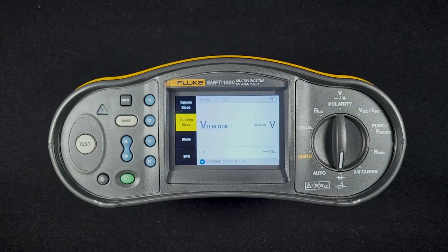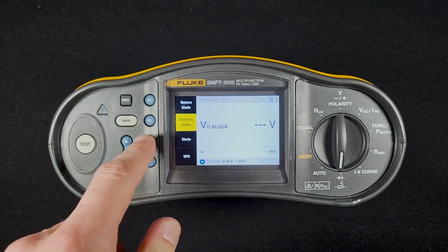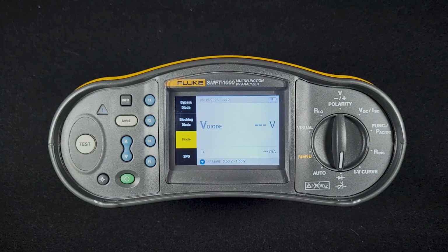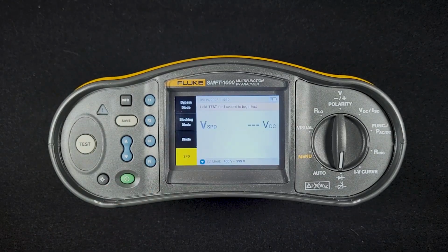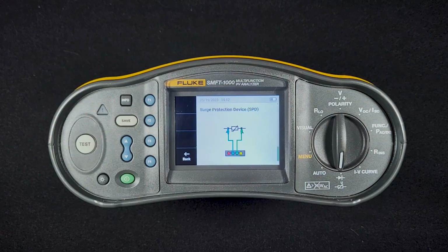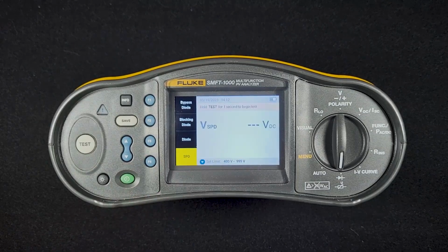We can also test blocking diodes, very similar to the bypass diode test. You need to get the manufacturer's information for what voltage should be going through that diode. We can also do a continuous diode test. If we had lots of diodes to test, we would use this one where we can just go point to point and test those diodes. We can also test our surge protection devices to ensure that they're working properly. Again, we want to go and find the manufacturer's data of the surge protection device and see what the voltage through that surge protection device should be. We can hit the info button and see how we're going to set up our leads when we do that test as well. So handy thing if you're doing bypass diode testing in the field or you want to test your surge protection device.